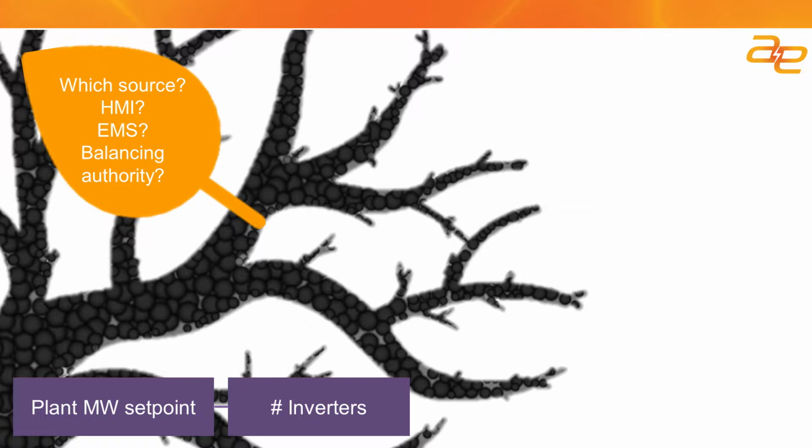So now we have an active power command, but you might have multiple sources of command for active power. It might come from the local HMI screen, where somebody sets that you want 100 megawatts of output. It might come from an energy management system where the owner of the site is sending a command that they want the site to run at. Or there might be a feed from the balancing authority that has the ability to turn down or curtail your site automatically. So you have multiple potential sources of your set point for active power, and you'd have to choose by priority which one you want to follow and when.